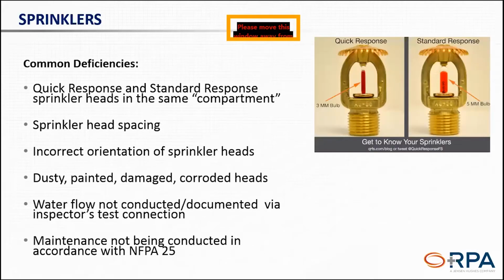More about sprinklers, some of the common deficiencies we see. Well, sometimes we see quick response sprinklers and standard response sprinklers in the same compartment. Now, compartment is a very interesting term when it comes to sprinkler placement. A lot of times in healthcare, when we're talking about compartments, we're talking about smoke compartments. That's not what this is referring to. A compartment, when it comes to sprinkler protection and NFPA 13, they define as basically an atmospheric compartment. So, a room or a space or an area, a part of a hallway.